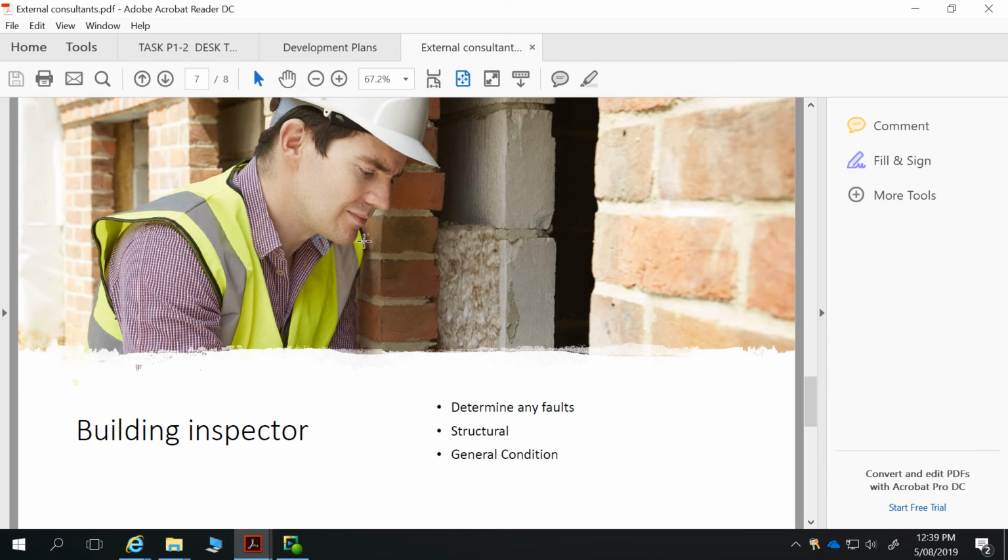But there's also going to be a whole host of other things that may not be easily seen. Another thing which is really common with old buildings is salt damp and moisture issues. I've seen time and time again moisture issues caused by people blocking up ventilation. Old houses that had strip footings and dwarf walls and suspended timber floors over that require ventilation underneath to help get rid of moisture. Those vents are bricks with little holes in them on the outside of the building, up above the ground.